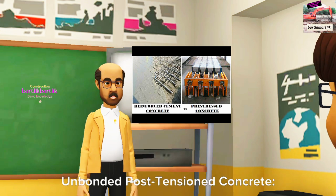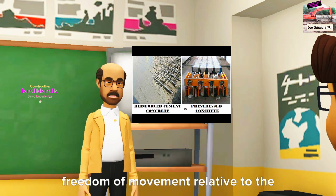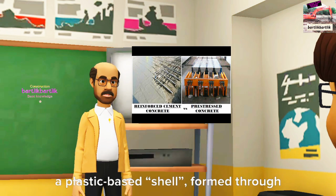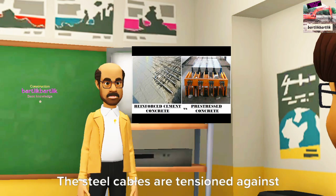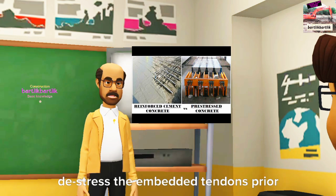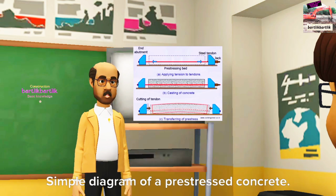Unbonded post-tension concrete. Here, the individual tendons retain freedom of movement relative to the concrete. Tendons are prepared with a coating of lithium-based grease, then given a plastic-based shell, formed through an extrusion. The steel cables are tensioned against anchors placed in the slab's perimeter. This design provides the ability to distress the embedded tendons prior to repair. Simple diagram of a pre-stressed concrete.